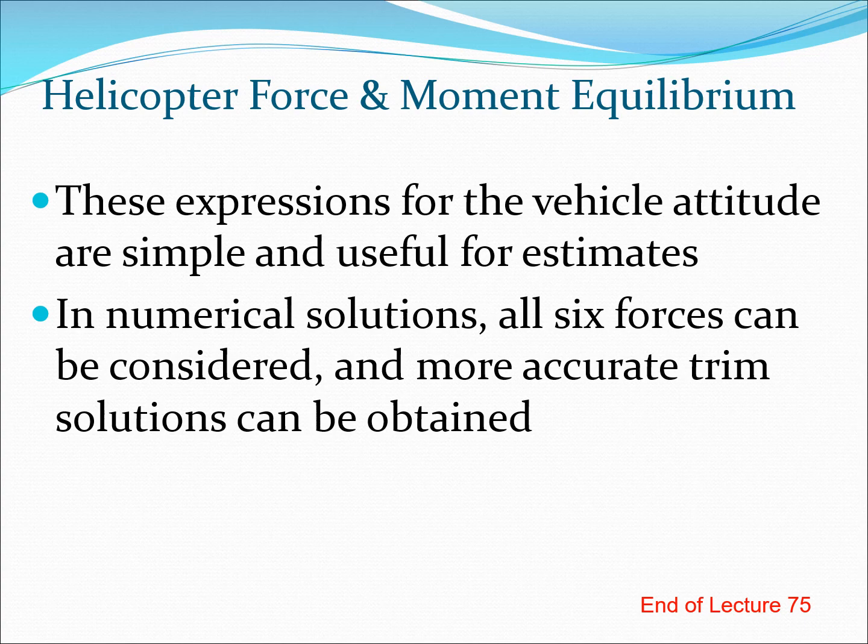solution of the trim equations is required to calculate the response correctly and therefore calculate the helicopter loads, vibration, bending stresses, and so on. Because depending on the value of the different trim controls and the vehicle position, the loads are going to change on the flight vehicle.